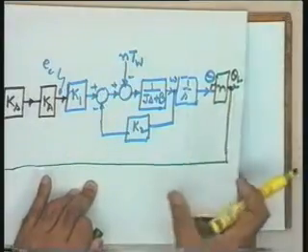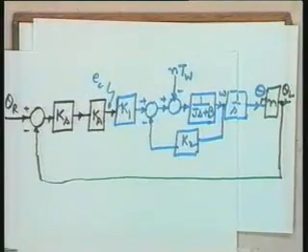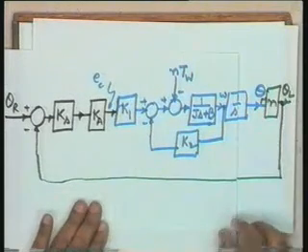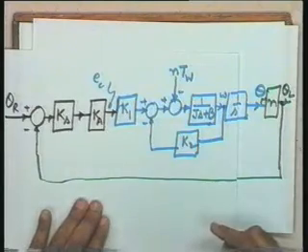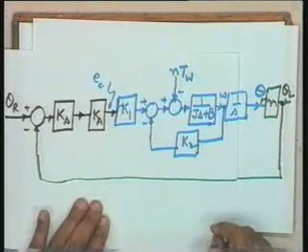The block diagram now should be seen in this way, wherein the output is theta L, the position of the telephoto camera, and the input is theta R, which is the position of the spotting scope. So what you require is, when you move the spotting scope, the telephoto camera should automatically move without any transients. You have to suppress the transients so that it should not oscillate, and at the steady state, the accuracy should be as you want, that is theta R should be equal to theta L, the steady state error should be reduced to 0. This is what you want, and this is the control design problem.